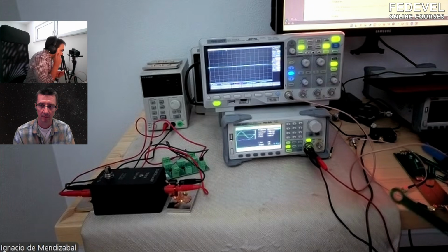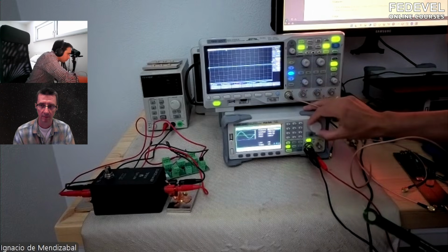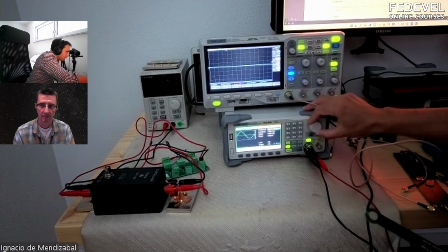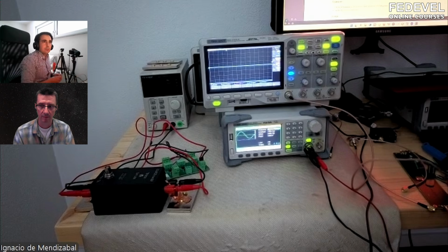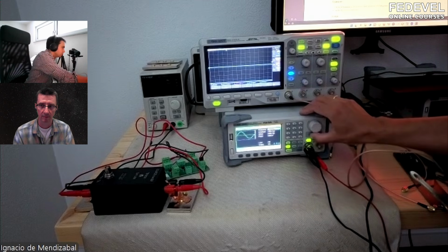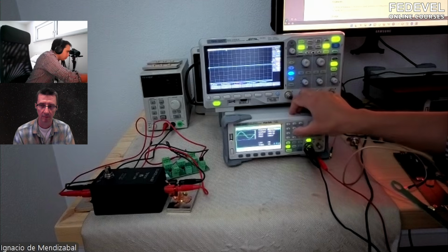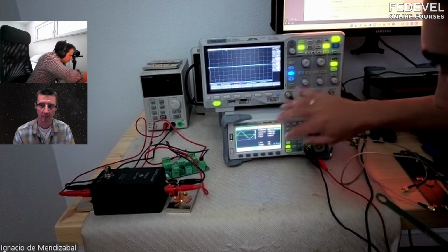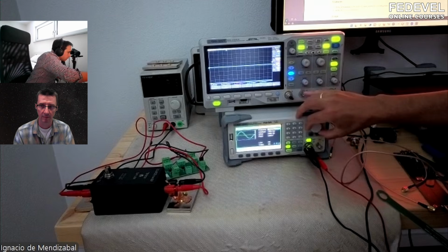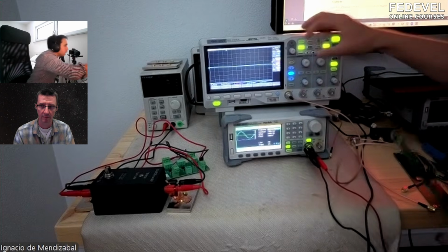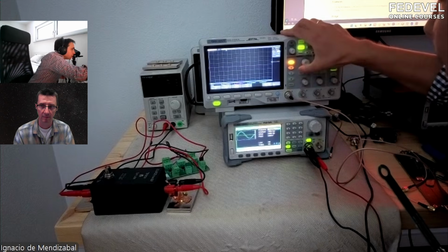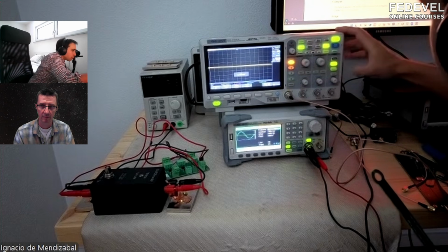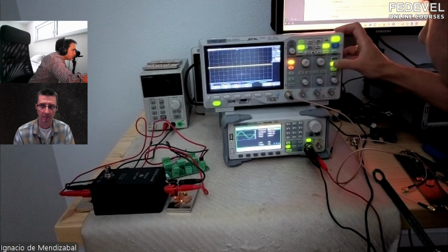Here the signal is 20 kilohertz, and we are going to go to higher frequencies. You know that normally radiated frequencies are more or less in the megahertz range. So we are going to inject a signal. Let's start, for example, with 2 MHz. So this is what we have right now. At the same time, we're going to measure just channel 1. We're going to disable everything, and we're going to see what we see here.